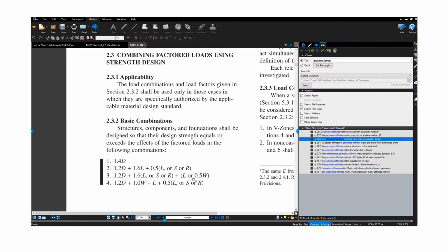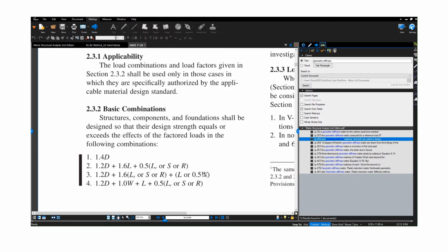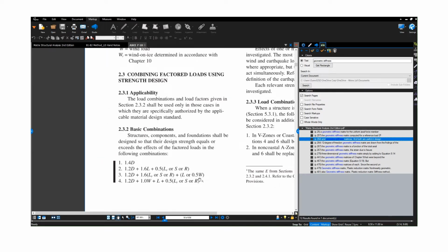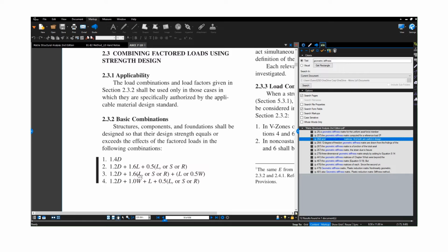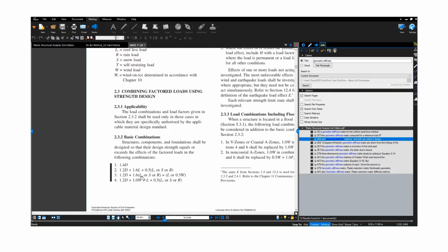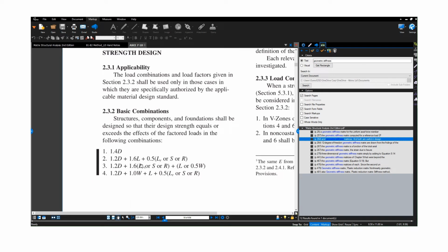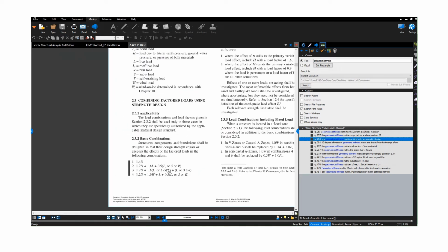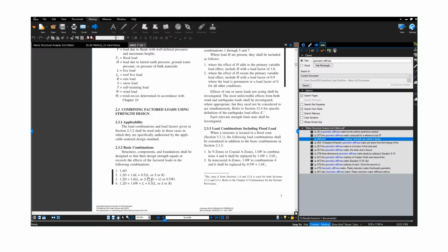This other load combination, number 3, involves using wind, but you'll be reducing the wind load by a half and increasing your load factor for the live load by 60%, here using 1.6. That's not likely to be the controlling load case.